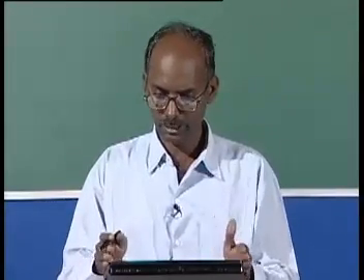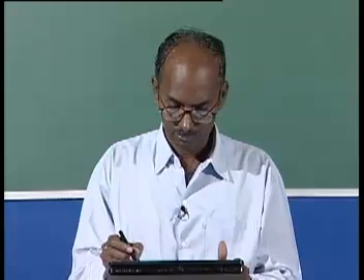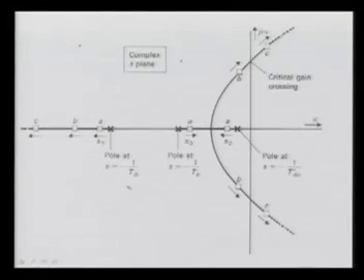So let us see now the overall root locus plot. This is the complete S plane, where this is your real axis and this is your imaginary axis. We saw that this pole at x is equal to minus 1 upon T'do is related to your generator. Here this pole was your exciter, 1 upon T, and this pole was for your gain.